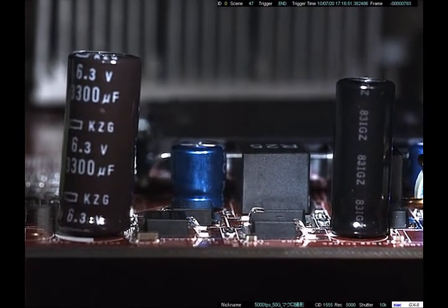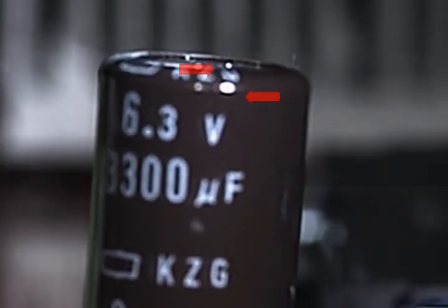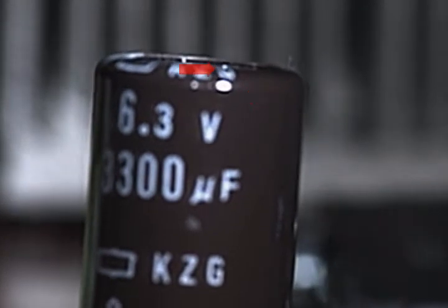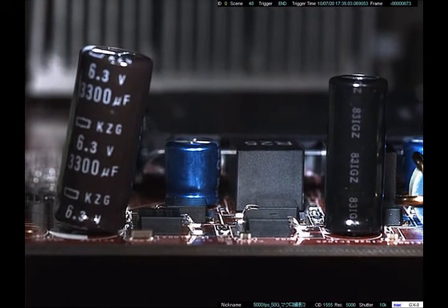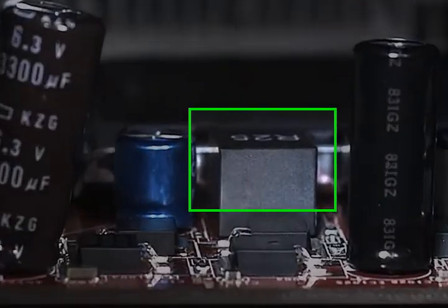A closer look at actual component excitation shows that the shocks are making the components move at their own resonant frequencies, in multiple axes. The larger leaded components, with lower resonant frequencies, experience wide excursions as they resonate. Smaller components, with high resonant frequencies, can be seen responding to the individual actuator strikes with a displacement and following ringdown.